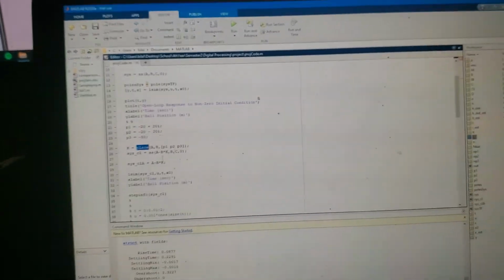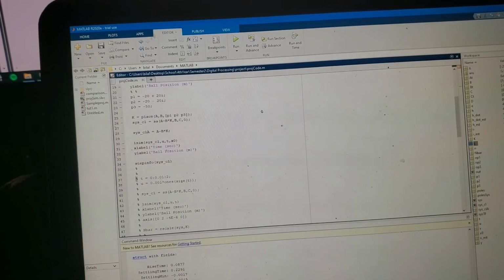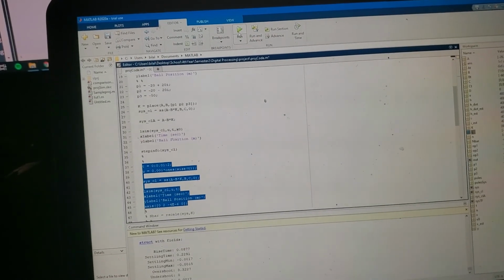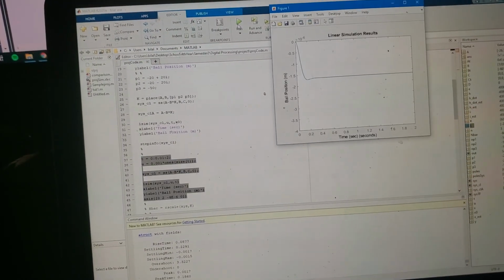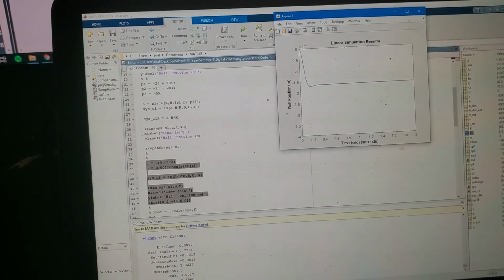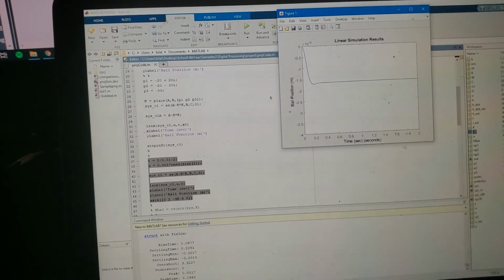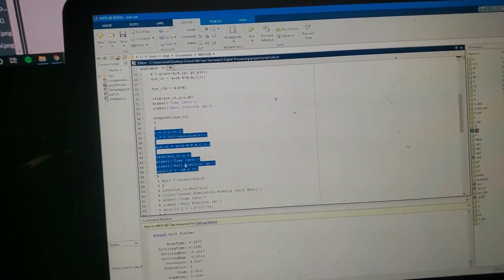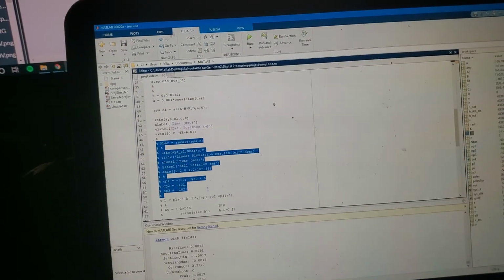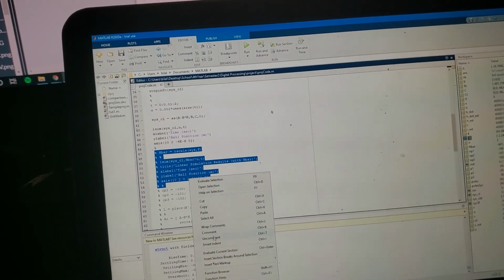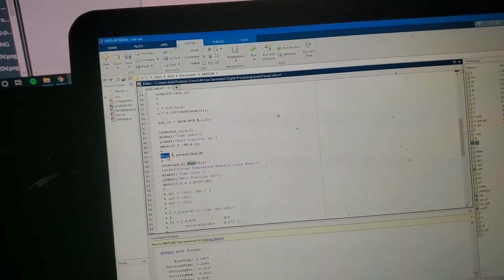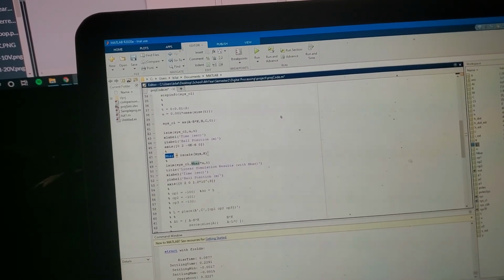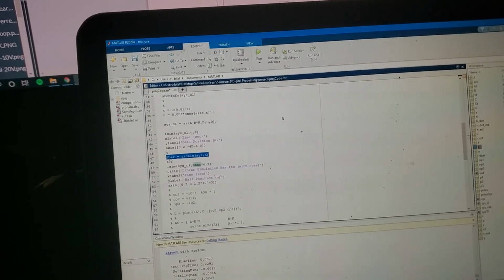Our next step was, as you can see, if you apply a unit step into the system, you're not going to get the controller to follow that unit step. There's a little bit of a problem there, and we decided to fix that using rscale. The function rscale is really helpful. As you can see over here, I'm going to uncomment this right here. This n bar is a scale factor for the controller. The following MATLAB code was used to compute that n bar value.